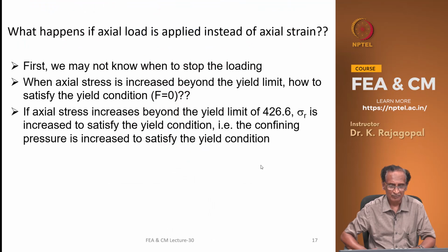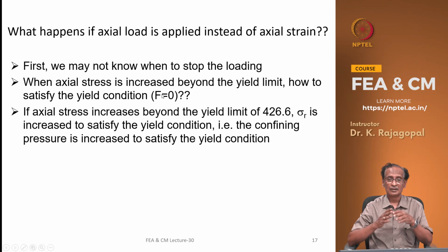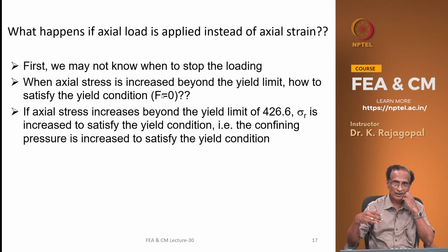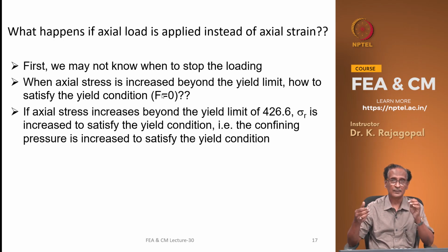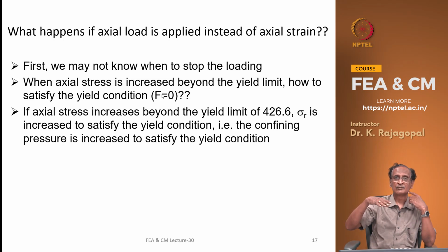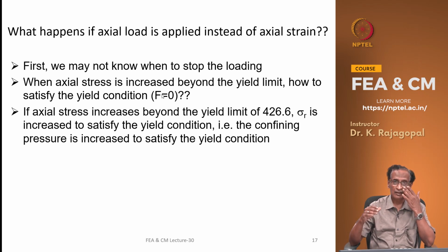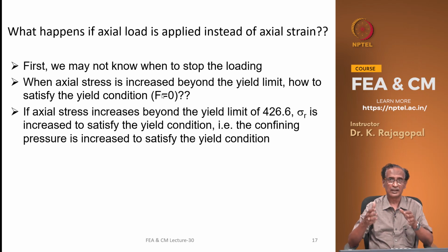So basically, when we use the load control analysis, we may not be able to get convergence. Here we are only doing a single element triaxial compression test, but say you do it for a bearing capacity problem or for lateral earth pressures, the whole thing might deform a lot without any limit, because you are not constraining the system, and interpreting those results could be very difficult. Instead, if you apply displacement control, we apply some displacements and then calculate the reaction forces. We will see with an example in the next class what happens when you do a bearing capacity problem by applying uniform displacements or uniform pressure. Okay.